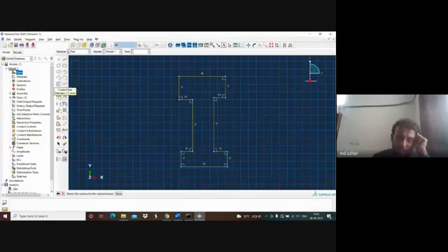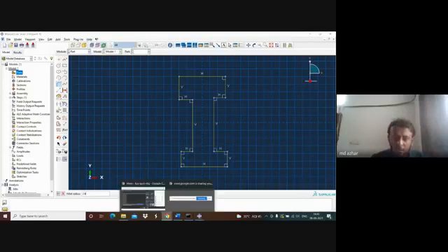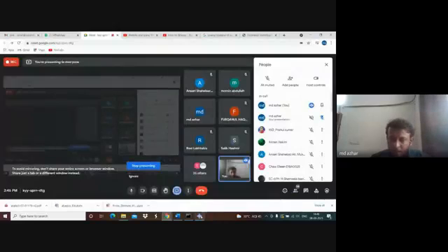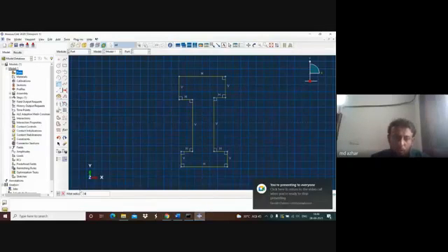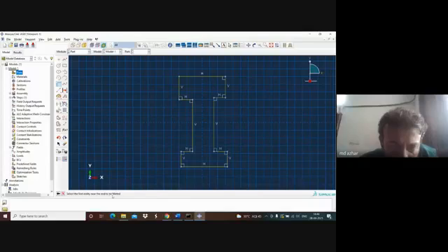That is the fillet. We have to give a fillet over here. So I click on this. This is the fillet part, and you can give the fillet radius at the bottom of the screen. Let's suppose I give a fillet radius of 2. Now you enter it. Now it is asking to select the first entity near the end to be filleted. Suppose you want this to be filleted.